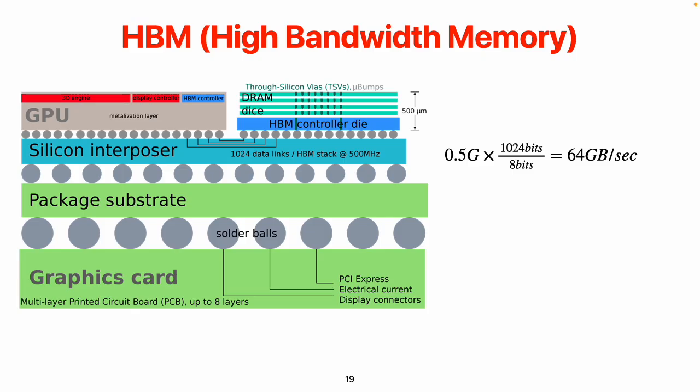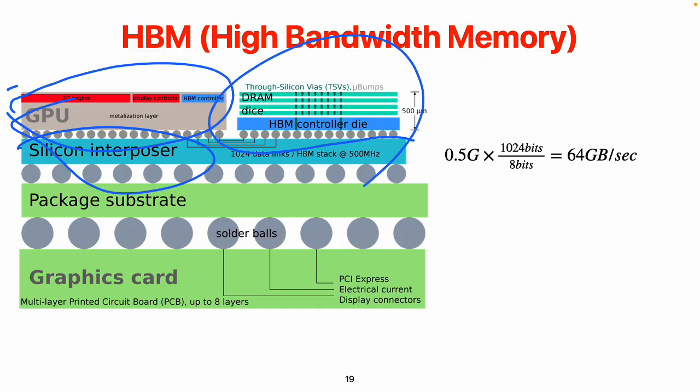since we have more advanced packaging technologies, what if we stack them together as a single chip? You might be wondering, what's the benefit of stacking them as a single chip? So this figure tells you why. If you are using a silicon interposer to connect your GPU die and the DRAM die as a single chip, because it's a silicon substrate on a chip, the wires can be made smaller.